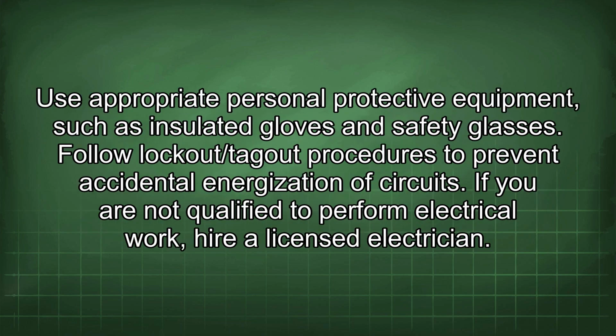Use appropriate personal protective equipment, such as insulated gloves and safety glasses. Follow lockout/tagout procedures to prevent accidental energization of circuits. If you are not qualified to perform electrical work, hire a licensed electrician.